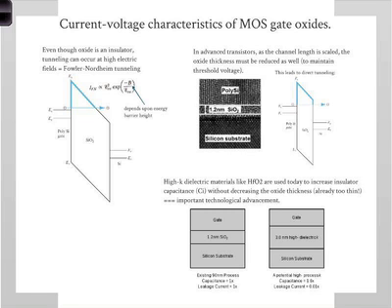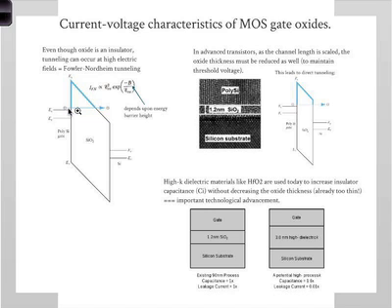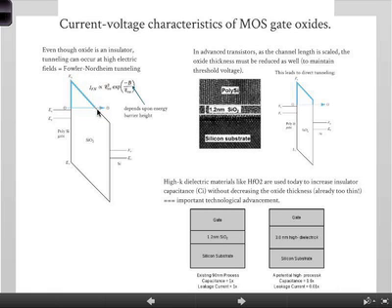But first of all, even for conventional devices, you can have a situation. This is the energy band diagram. So you have a polysilicon gate, let's say. Okay, Fermi level, valence band is here, conduction band is here. That's pretty much the Fermi level because it's heavily doped. So heavily doped means the Fermi level is almost right at the conduction band, pretty much, right? Now, you have some electric field on the oxide, and then you have on this side silicon.